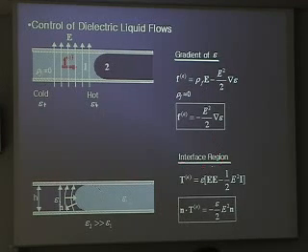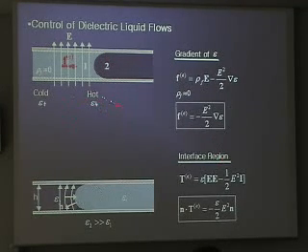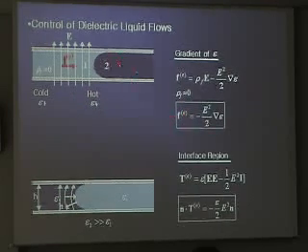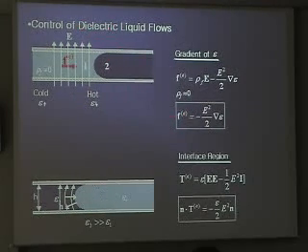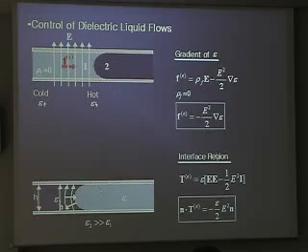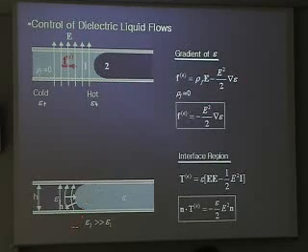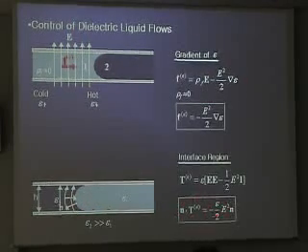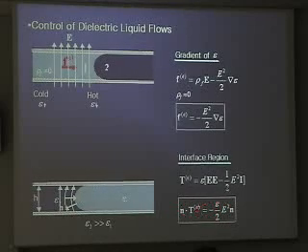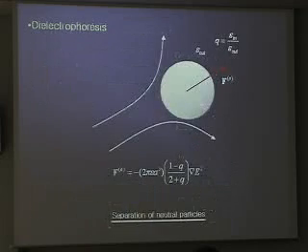Among several terms of electromagnetic forces, dielectrophoresis uses this term, the polarized one. So if you have some distribution of electric conductivity inside the fluid, by simply applying an electric field, you can control the flow. And sometimes if you have an interface, you can make a certain interface force, okay, surface force, by using this one or a combination, we can control the flow.